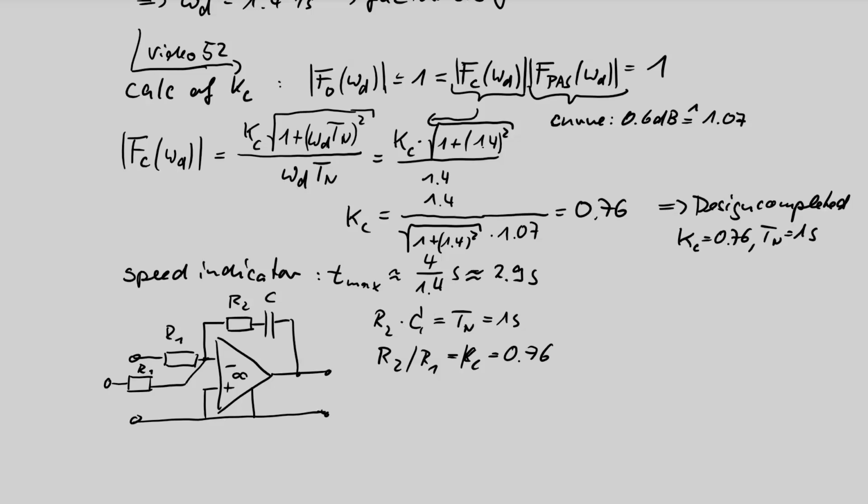The capacitance should not be an electrolytic capacitor. The largest possible non-electrolytic capacitor which can be bought is 10 microfarad, but this is also a big thing, costing roughly 10 euro. So it could be a good idea to make C a selection smaller, say C is 1 microfarad. Then we can calculate R2. R2 then is 1 megaohm.